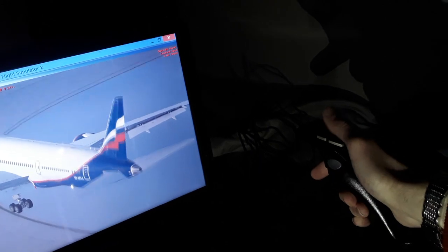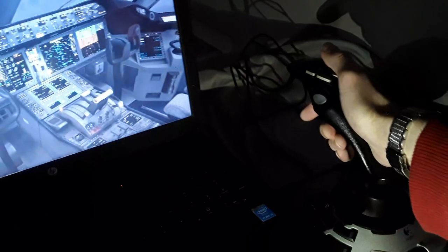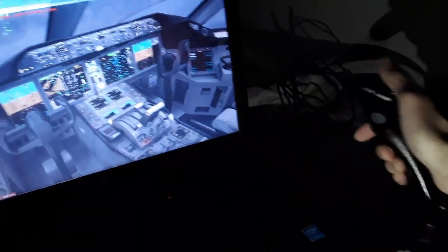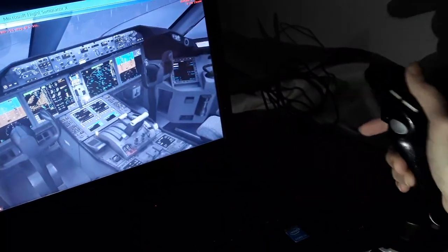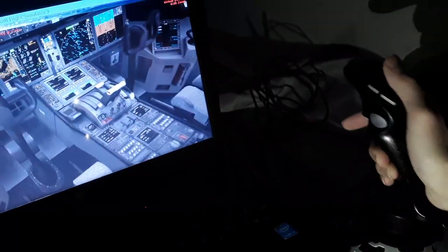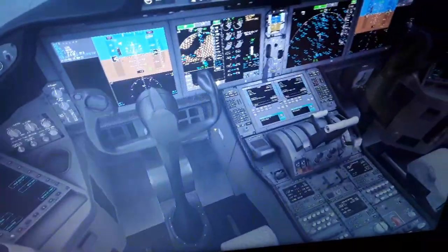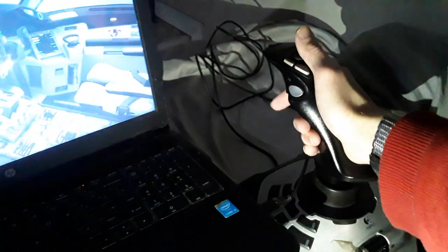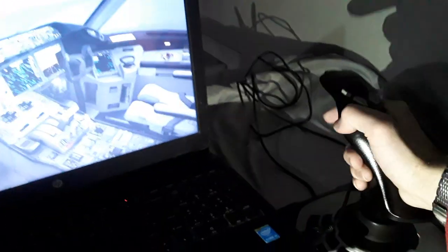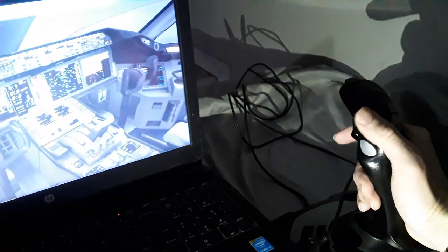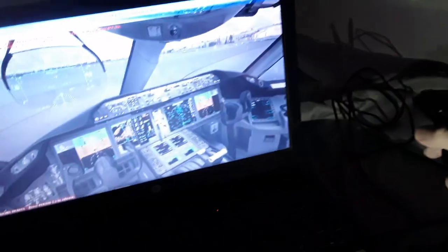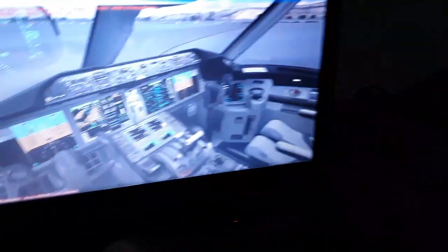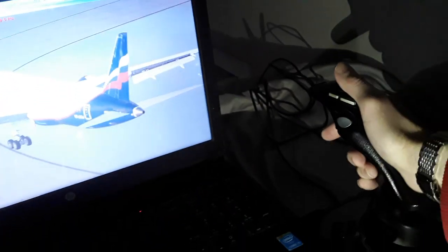You can see the control column over here in the Boeing. You climb and descend, moving the side stick in the Airbus back and forth. The Boeing has the control column, the yoke, like this, very easy. Both sides again are interconnected. The captain and the first officer always move together in the Boeing aircraft. In the Airbus you have the side stick priority button. You take either side control or dual input. So we have the elevator climb and descent.